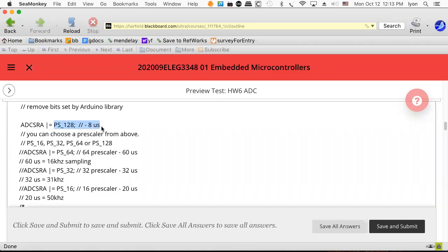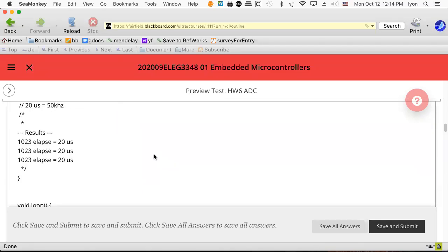And if you took the 104 microseconds and said 1 million divided by 104, you get 9,615 hertz, which is 9.6 kilohertz. So that's kind of how I approach that. A couple ways to do that.